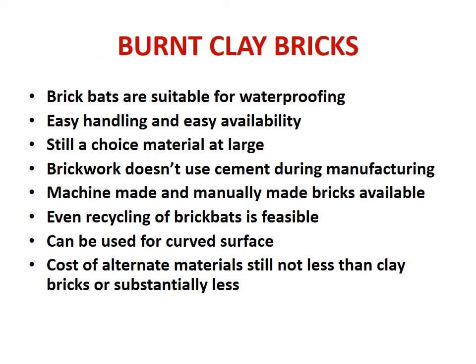And then advantages are many of burnt clay bricks, though it's not a green material. Brick bats are suitable even for waterproofing, plinth protection and all that. So even if a brick has broken, then also it is used. Almost nothing goes waste in burnt clay bricks, and there is easy handling and easy availability all over the country, and still a choice material at large in private construction, particularly small size constructions.